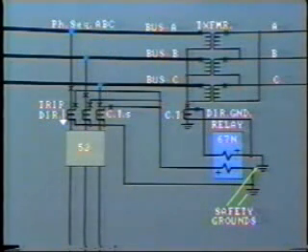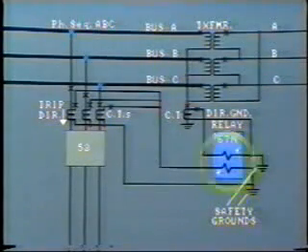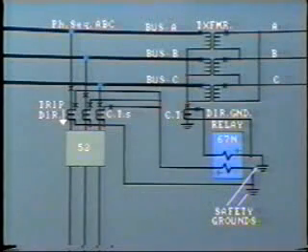You can see how important it is to get polarity right when making connections. If either of these relay connections is reversed, the relay would perform completely opposite to our needs. It would allow tripping for ground faults outside the zone and would block tripping for those within the feeder.